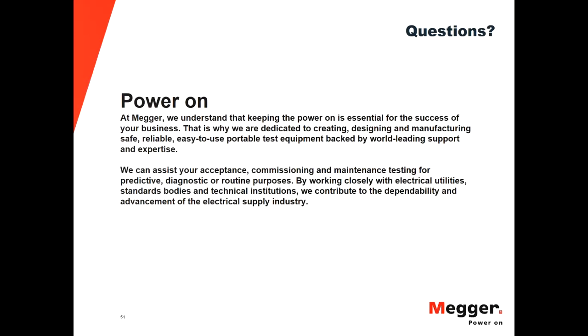All right, next question. When performing the capacity test or load test, is the battery totally disconnected from the DC system? So as Volney just said, it's important to have a backup battery to be safe from an outage. But let's say you have a load, you don't have a backup battery, and you want to do a discharge test on a battery bank. You can do that. The battery will be disconnected from the charger, of course, because you don't want to be discharging the battery while it's being charged at the same time, right?